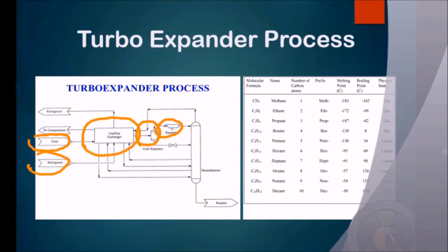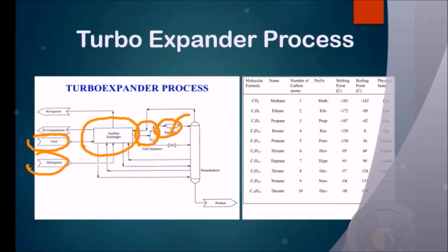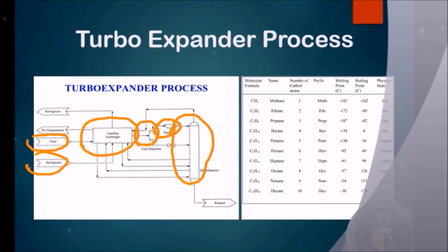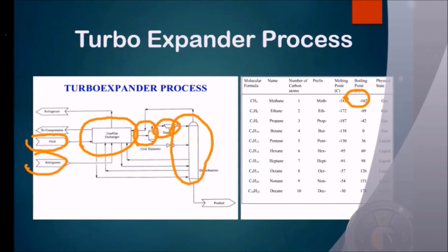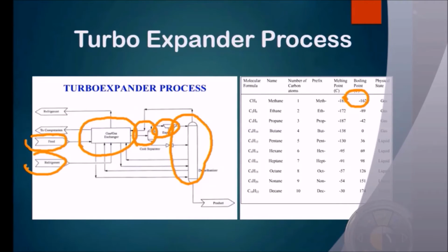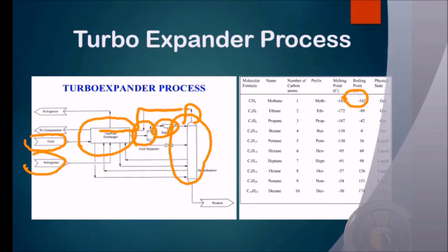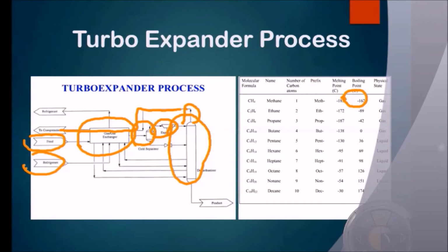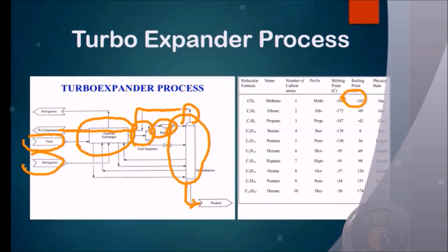To separate the methane from the natural gas liquid, the liquid mixture is passed through an additional chamber, the demethanizer, this one, where it is progressively warmed. Since methane has a lower boiling temperature, which is -162 degrees Celsius, compared to other hydrocarbons, methane will vaporize and leave the tower here, all the way back to the compression process, and the natural gas liquid will be extracted from the demethanizer.